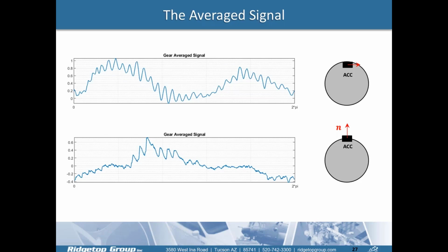But anyway, this transversal is actually what has been measured on the bearing so far, and all the fault diagnostics have been based on this. So it's not like there is no information in this signal, it's just that the torsional one has a better and a stronger signal. Next slide, please.